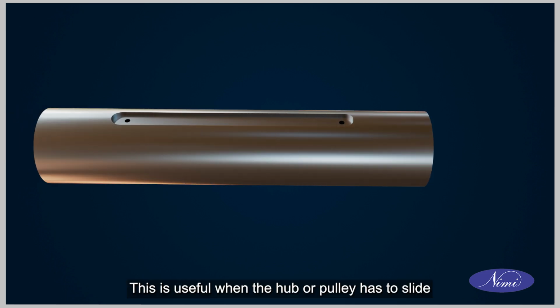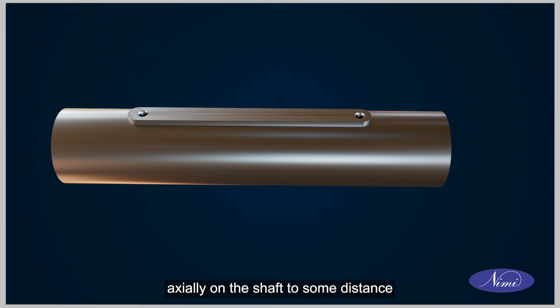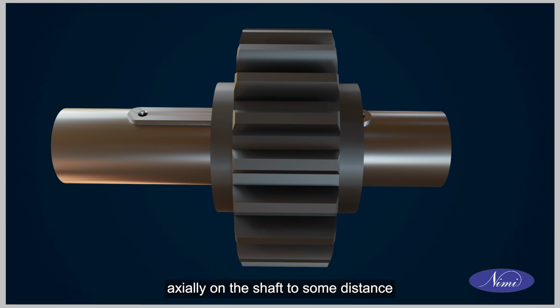Feather key. This is parallel key with rounded ends. This is useful when the hub or pulley has to slide axially on the shaft to some distance.